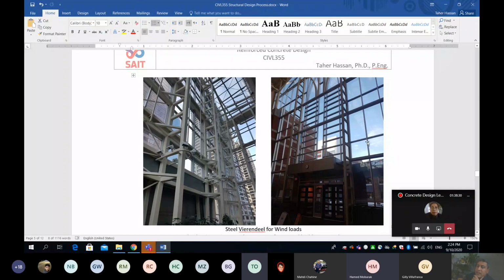No, you can't. And the reason why we can't, can I hear why we cannot call this a truss? Diagonal is missing. Exactly. You can see there is no diagonal from top to bottom. So how can we make it stable? Look at my finger. There's only one way, which is the connection between those horizontal and vertical members. It has to be a moment connection, a connection that can resist rotation.